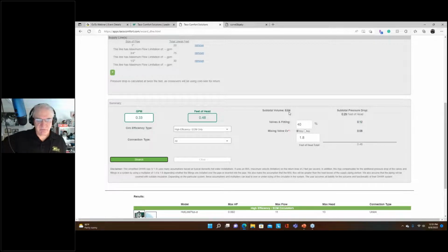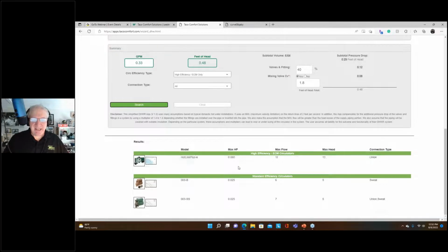In this case, making sure we insulate our hot water pipes will be very critical. All right, so 5 minutes on, 10 minutes off, 5 minutes on, 10 minutes off is where we're at now. It's going to take a couple of cycles to get our hot water line all set up. So if we look at that, okay, we're fine there. Now, even if we looked at other circulators, it really wouldn't matter much because we're still at that 0.33 GPM limit.